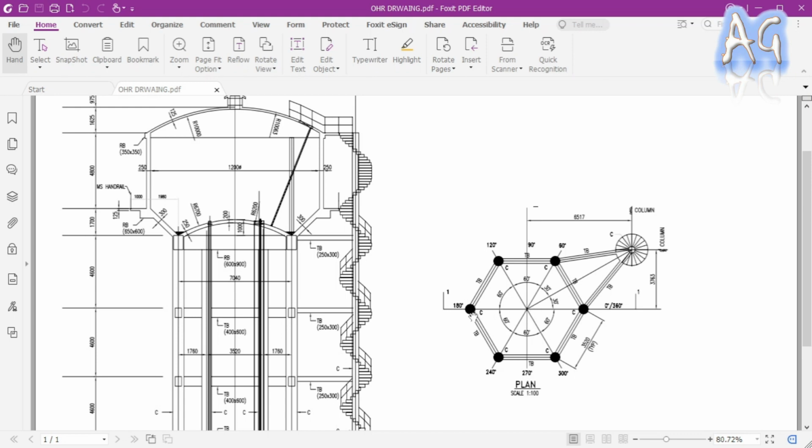Now this column center is situated at a 7.04 divided by 2 meter distance from this node along the x-axis. First I'm going to create this node, then I'm going to repeat this node in a circular way so that I can create all the nodes for all the column members. Now let's do it here.